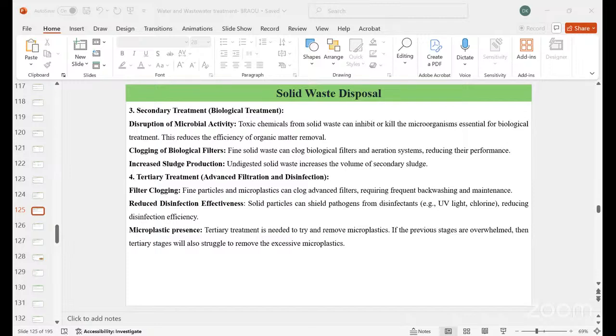Coming to the type 2 waste, which is defined as refuse, it consists of an approximately even mixture of rubbish and garbage by weight. This type of waste is common to apartment and residential occupancy, and it consists of about 50% moisture, 7% incombustible solids, and has a heating value of 2390 kilocalories per kg as fired.